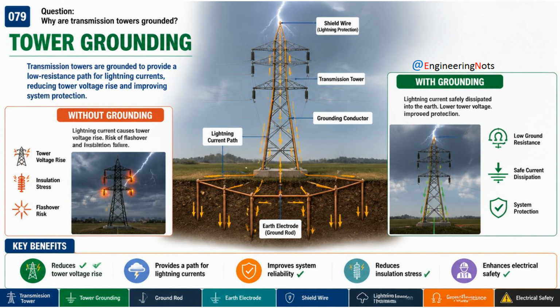Question 79. Why are transmission towers grounded? Transmission towers are grounded to provide a low-resistance path for lightning currents and fault currents to flow safely into the earth. If a tower has high grounding resistance, a lightning strike can cause a significant rise in tower voltage, increasing the risk of flashover and insulation failure. To minimize this problem, ground rods or earth electrodes are installed and connected to the tower structure, reducing the grounding resistance as much as possible. In summary, transmission towers are grounded to safely dissipate lightning currents, reduce tower voltage rise, and improve system reliability.